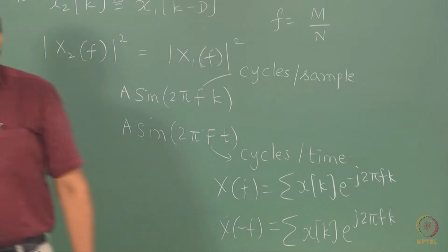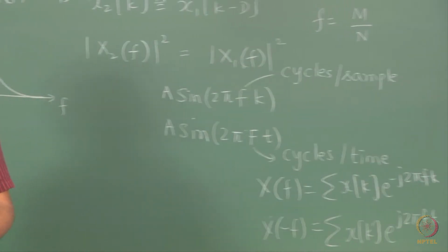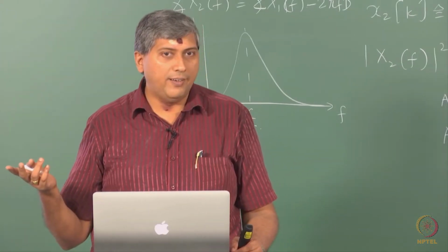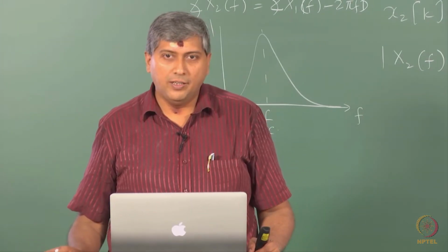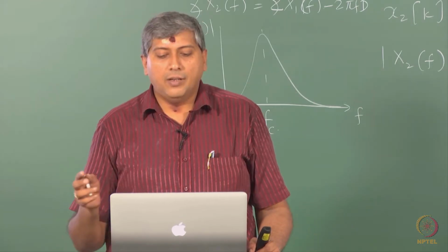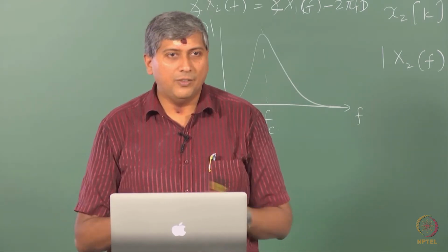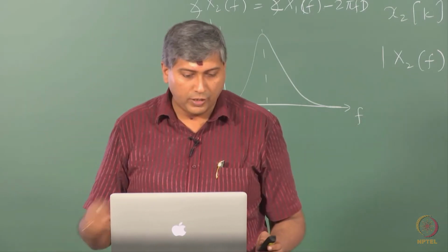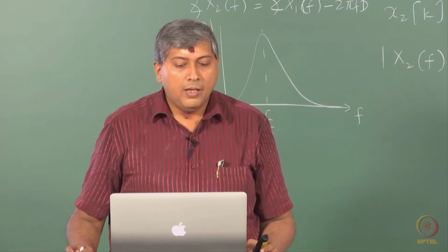Okay. So, flipping the signal in time amounts to taking a conjugate in frequency domain, and likewise you can see here, flipping in frequency amounts to actually flipping the time domain signal. So, the dual is contained in the statement.